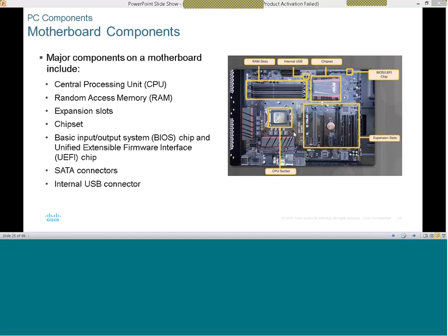With the legacy CPU we used to have, most of the memories are external, so the processor would actually have to go out from its domain, fetch information from an external memory, decode them, and then execute. But with a modern processor, you already have memories within them, which we call cache memories. And so there's a link between the cache memories and the external memory.